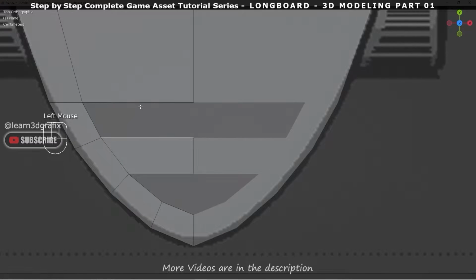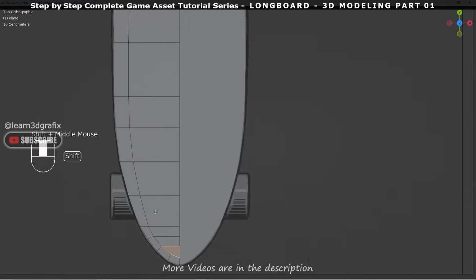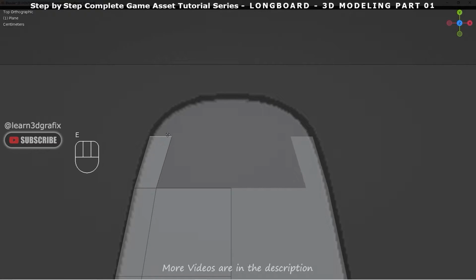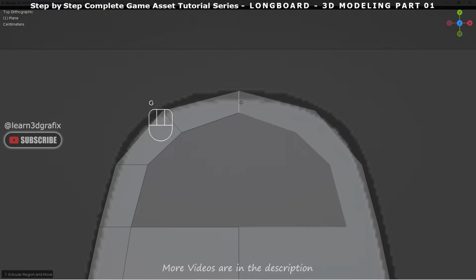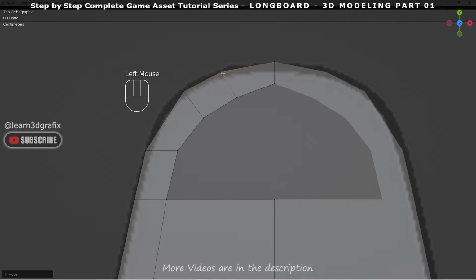Hold down Shift and select these two edges and press F to fill with a polygon. Now select this edge, press E and extrude the polygon. Extrude it one more time. Press E again and snap it to the middle. Now select this edge and press Ctrl B to bevel the edge. Move the vertices to match with the reference image.